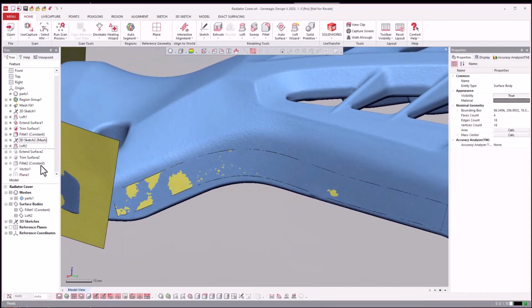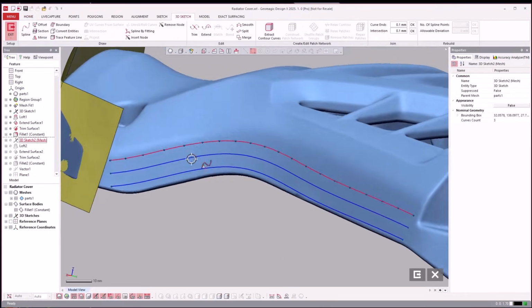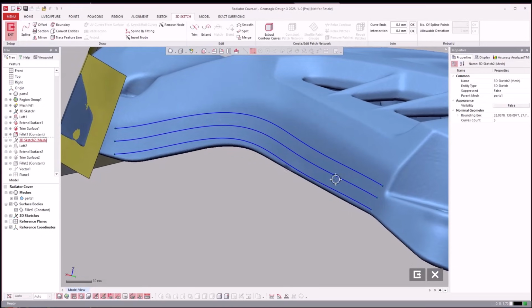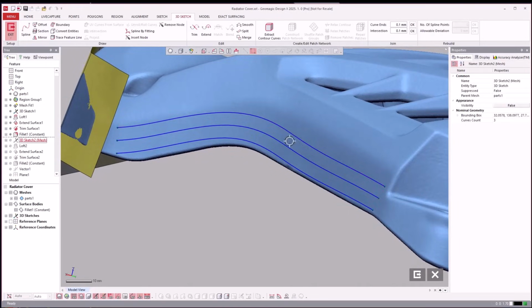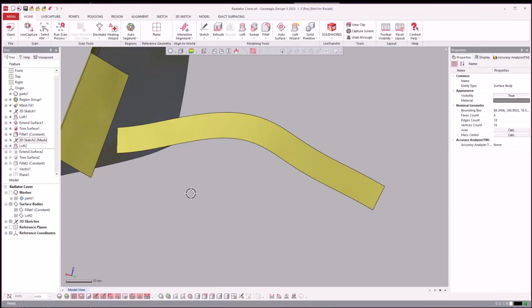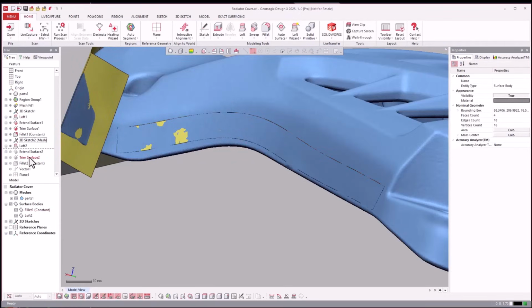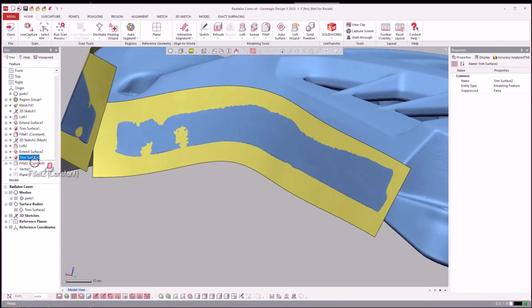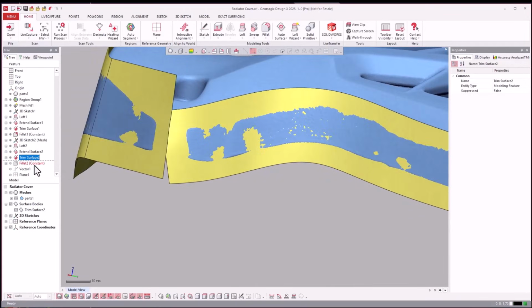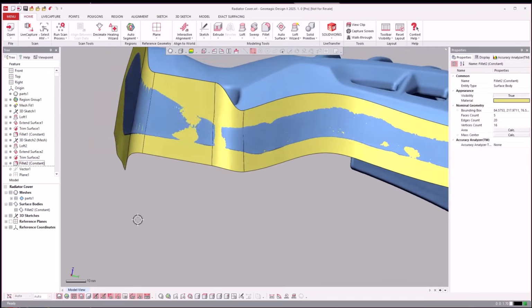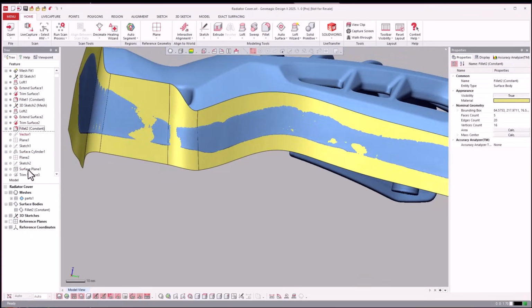So in this instance here, they just went in and drew 3 different lines. This is a popular approach that I see a lot of people do in here, where they draw these flow lines around and then they loft between those 3 down. So if I turn the mesh off, just do a loft down that direction. And then go ahead and extend, because you create a nice clean surface. There we go. And then trim those together.